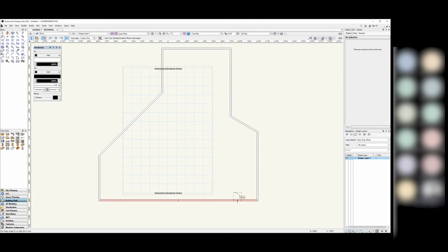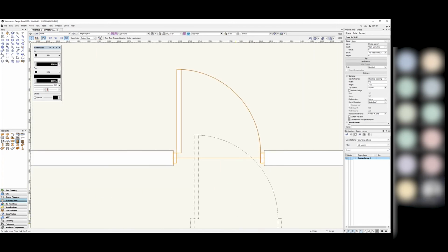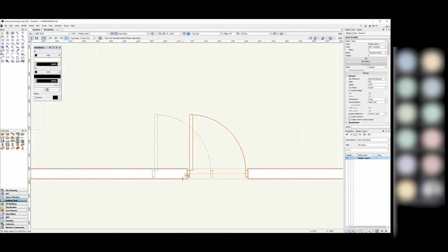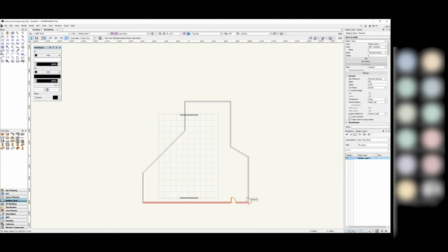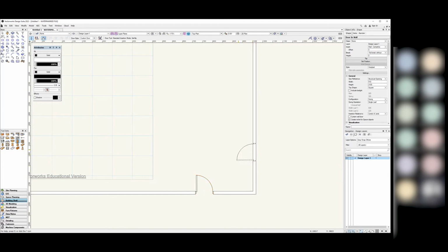So for instance, if I click on this wall down here, firstly, I can move my cursor left and right, so I can choose which way the door opens. I can also move it on either side of the wall to decide which way the door opens. So if I want it to open inwards, to the left, I'll bring my cursor over there, click to place, and that's now cut out my wall. It's removed that, it's placed in a frame, it's added a door, and it's added the span of the door as well. I can add in as many of these as I like.